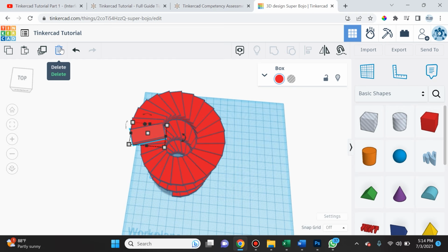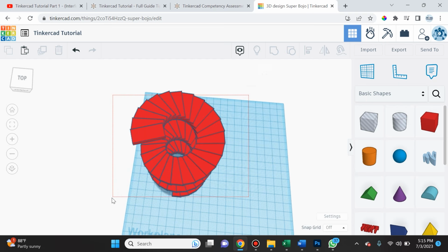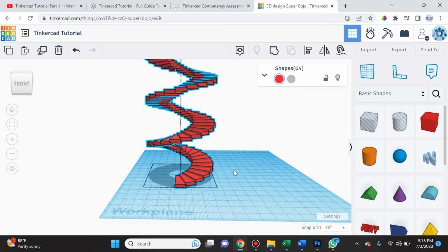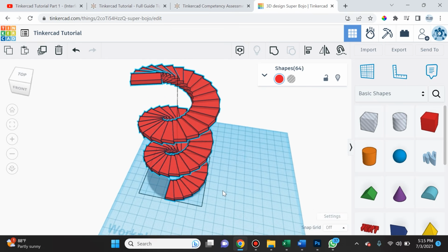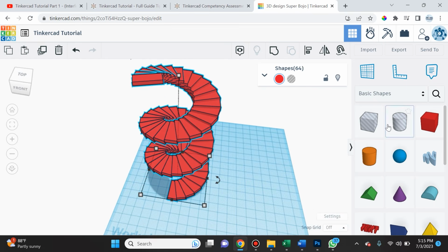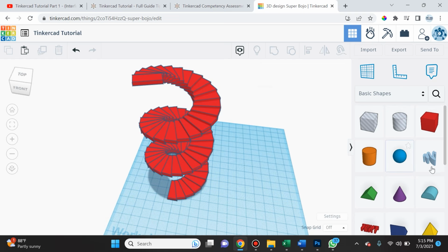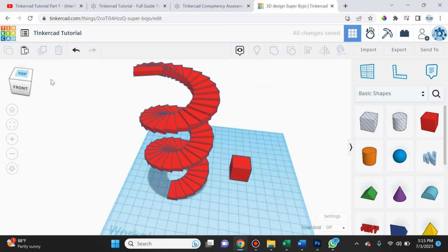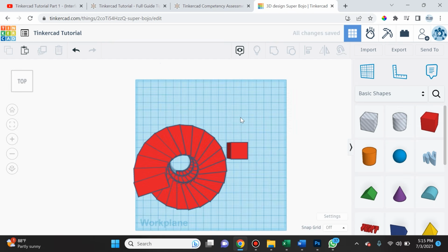And this right here, this is just trash. So remember, if you select anything, so let's say we want to select the whole thing, you could hold down left click and just select every single object that's here, and you will see that it all gets a blue halo, which means it was selected. And by the way, I want to point this out because it's very, very important. If you have another object here, you may think that if you select, so let's see the top or bird's eye view, if you select just this, you may think that only the spiral staircase will be selected.